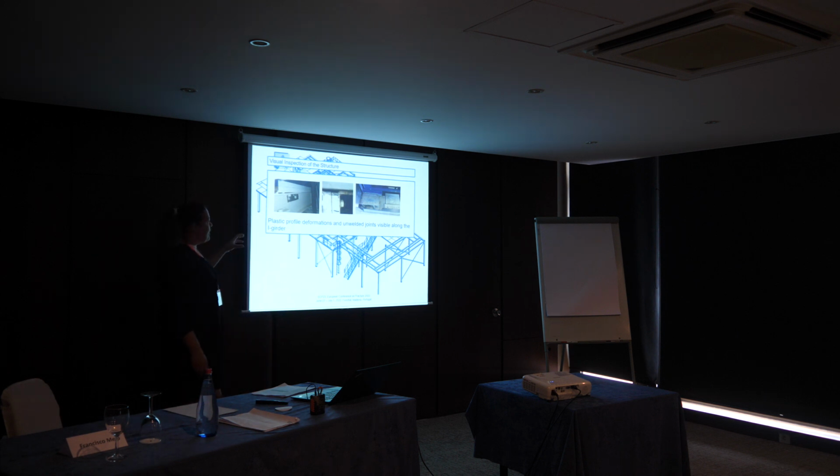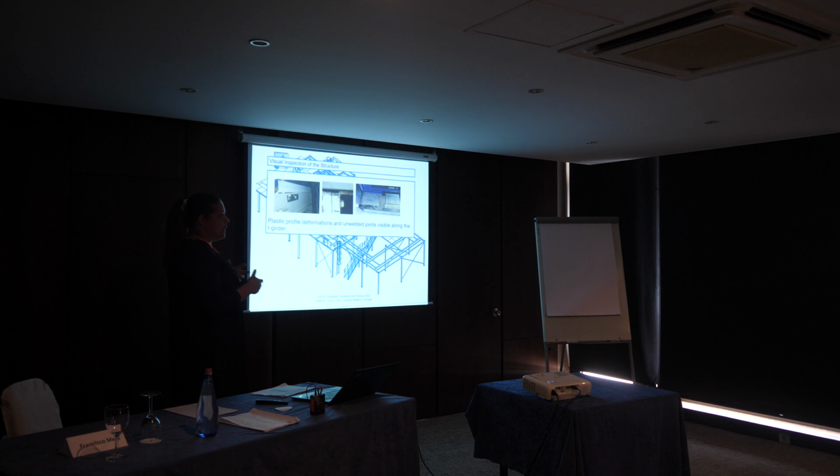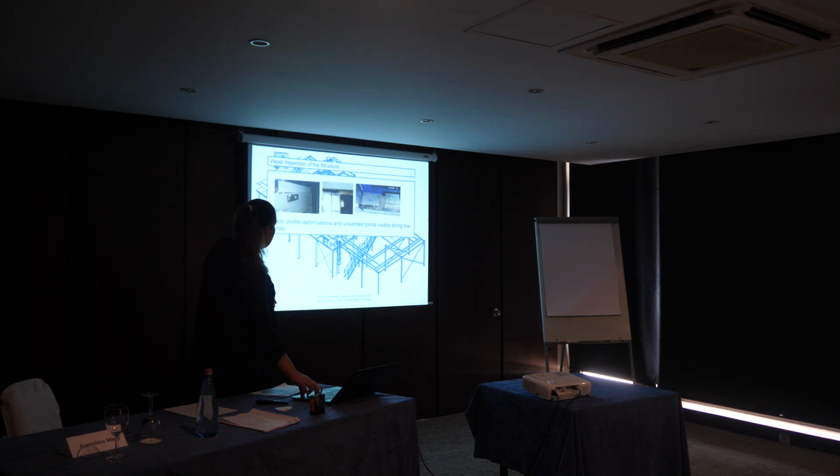Because maintenance and the installation of the construction were poor the first time, and maintenance, I think that they never did it. You have some girders that were plastically deformed, some screws were loosened, some welded joints were not done properly. When you need welded joints all along the girder, but you have welded joints on, I don't know, every 2 or 5 meters even. So we were prepared to have even worse measuring results than our computational results.